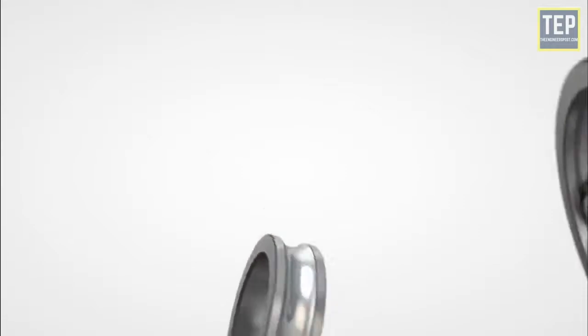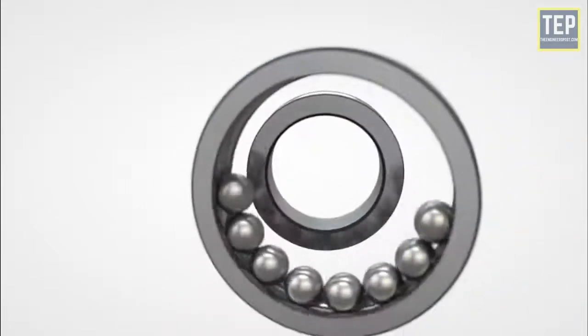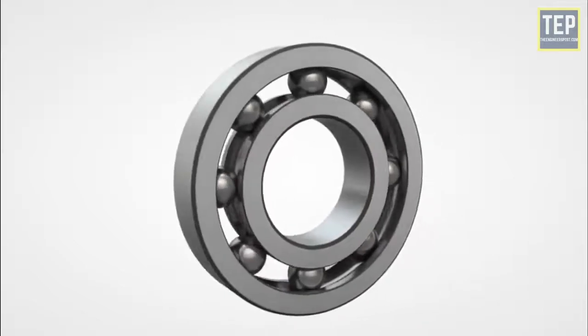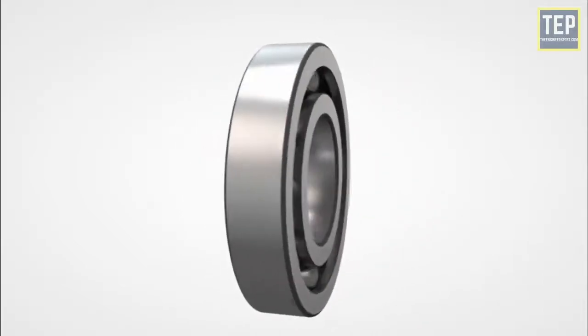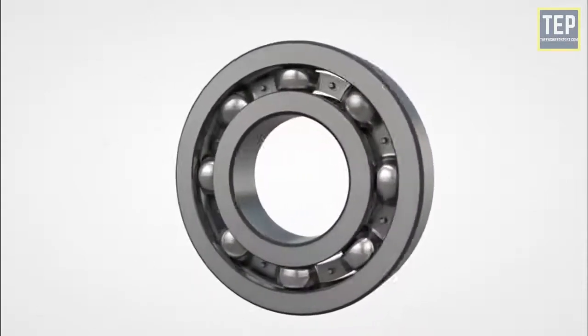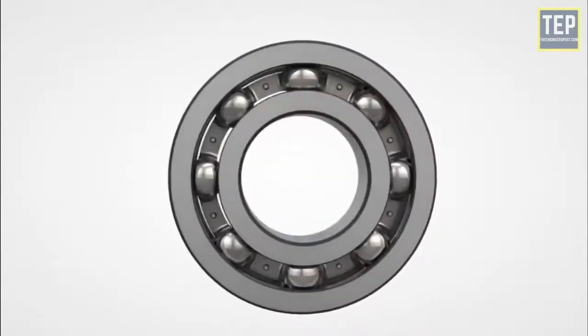Ball bearings provide very low friction during rolling, but have limited load carrying capacity. This is because of the small area of contact between the balls and the races. They can support axial loads in two directions besides radial loads.